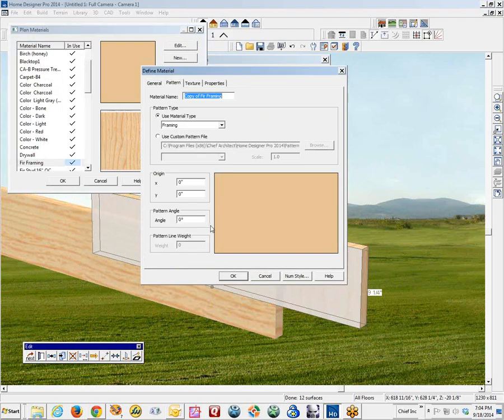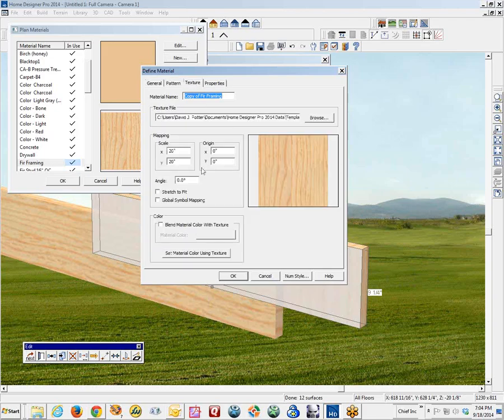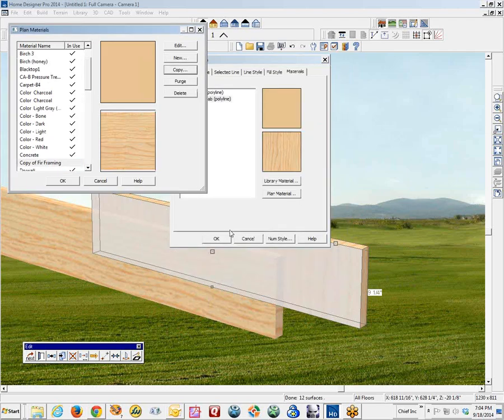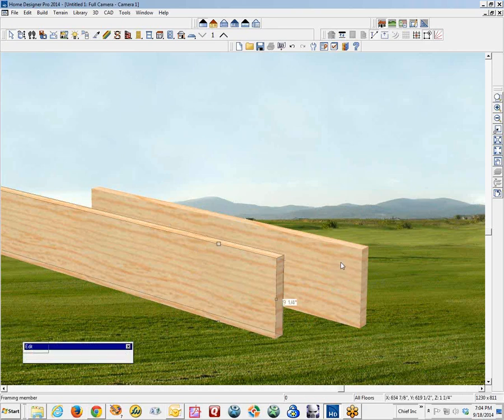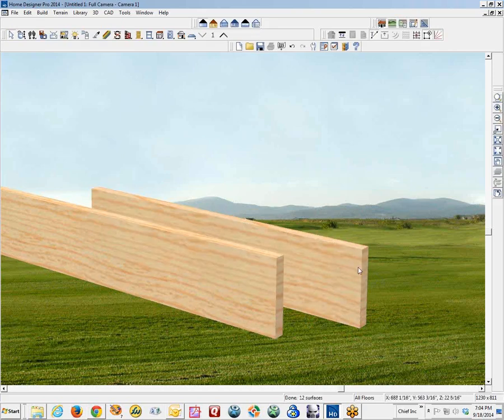Well, this is kind of an area, so we don't need to reverse that for vector view. So we'll go to the Texture and rotate it 90 degrees. And OK out of that, and that fixes that. Even though this material and this material are two different materials, it just paints differently across this framing object than it does this custom slab.